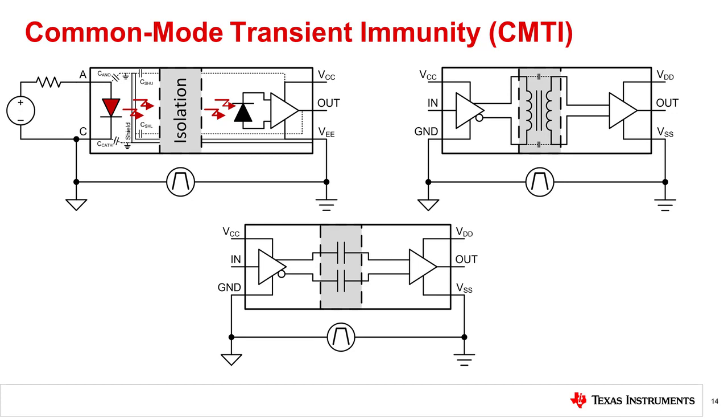Designers use internal die area to strategically place shielding layers and bypass capacitances, steering transients away from critical signals as much as possible. Since these structures are constructed on die, their effectiveness and the driver CMTI rating are affected by process, voltage, and temperature variations.